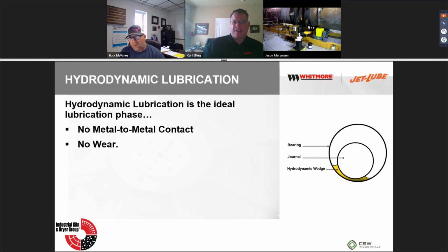Yeah, good question. On this one it's usually the viscosity of the oil. A lot of these things that you'll run into can range from an ISO 680, which is a very thick fluid, but you've got a lot of weight, and it's a slow-moving, heavily loaded type of application. So you'll want a thicker fluid. Sometimes, if you don't have the cooling effect like you do in the 680 environment, a lot of people will use an ISO 1000, so it's even thicker. And I've also seen an ISO 1500 fluid, which is even thicker than a 1000. All that's doing is creating a real thick fluid for high heat applications and heavily loaded ones. These things are pretty huge when it comes to the bearings, so you need a thicker fluid.